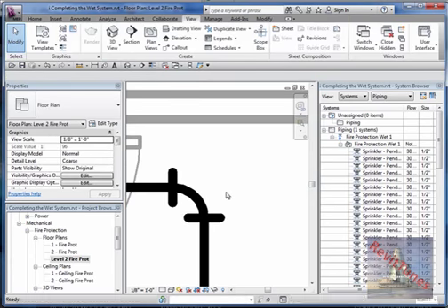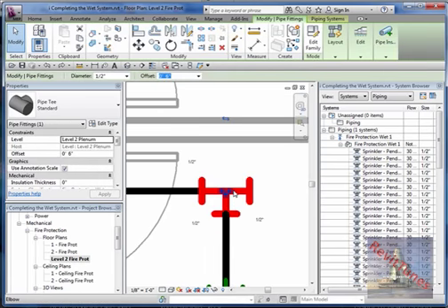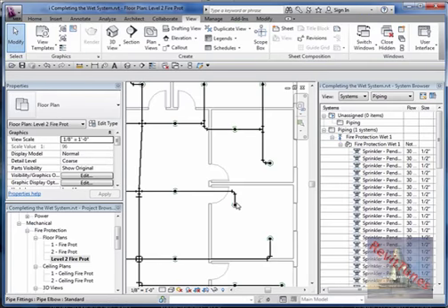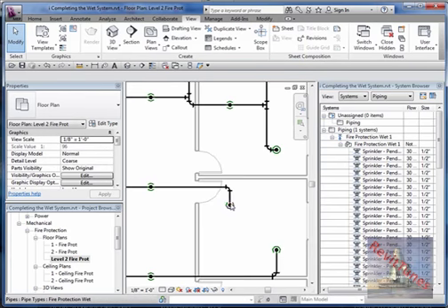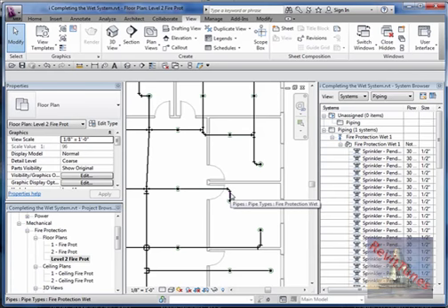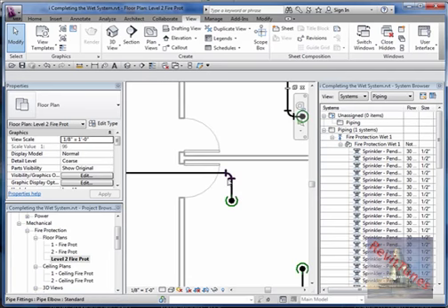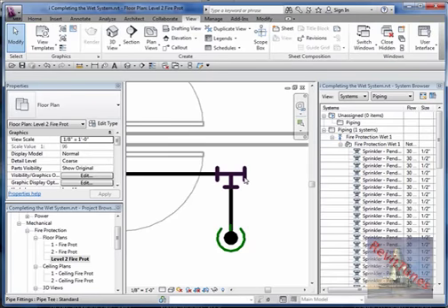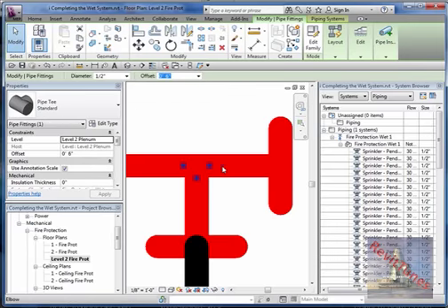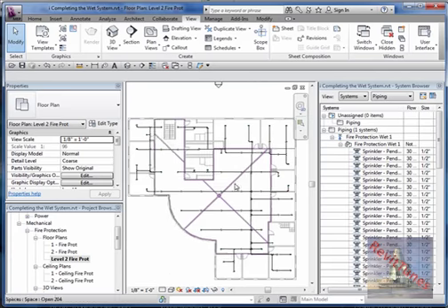Oh, I have to put a cap, but if I close this connector, oh, that's fine. I thought it was getting rid of the sprinkler, but sometimes you put a cap if it's at the end. But in this case, because at the end is a sprinkler, an elbow is good, and I close the extra connector which makes it a T. Because if I leave it as a T, it is open here, so you need either a cap or remove one connector and make it an elbow. Alright, now the whole system is closed.